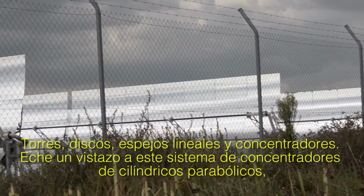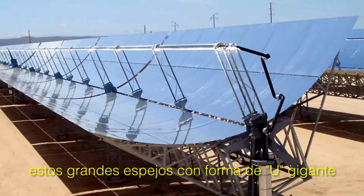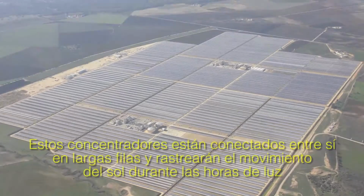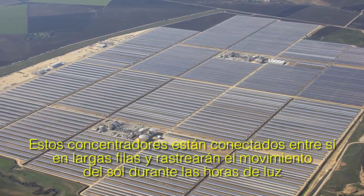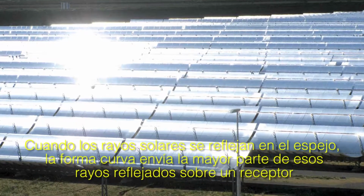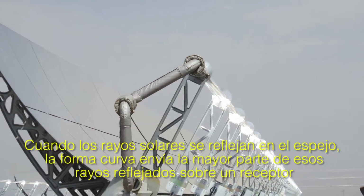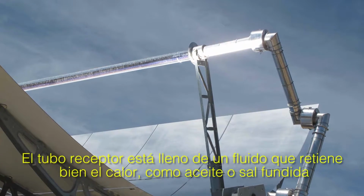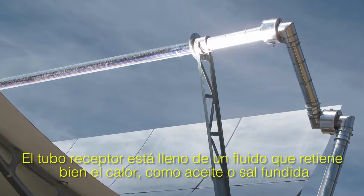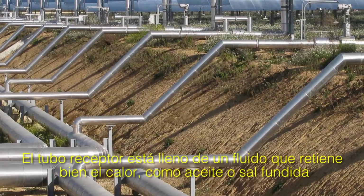Have a look at this parabolic trough system. Parabolic troughs are large mirrors shaped like a giant U. These troughs are connected together in long lines and will track the sun throughout the day. When the sun's rays are reflected off the mirror, the curved shape sends most of the reflected rays onto a receiver. The receiver tube is filled with a fluid that retains heat well, like oil or molten salt.